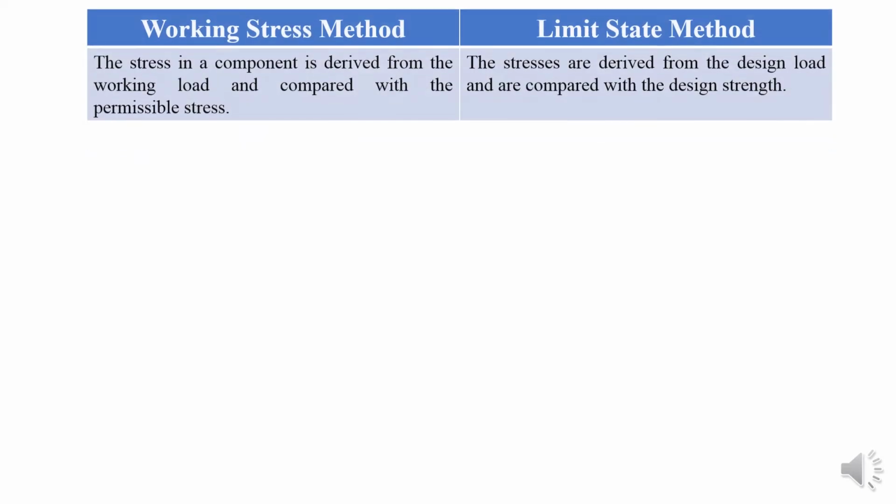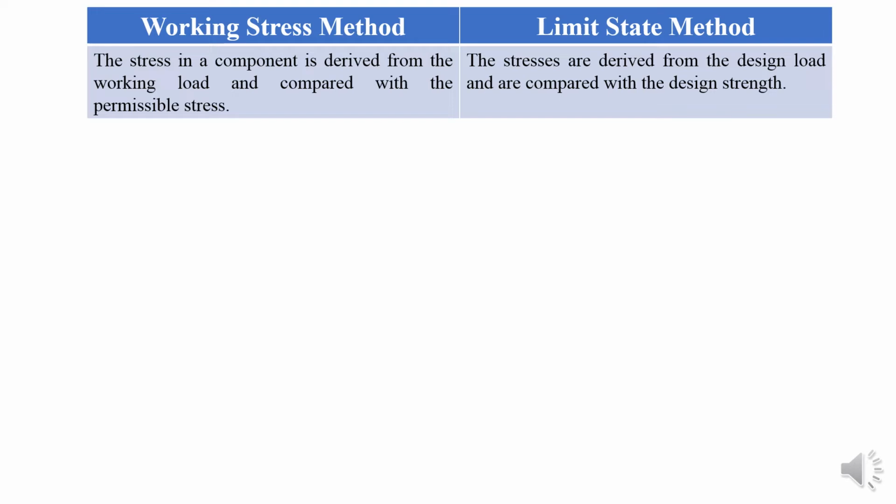We will see the difference between working stress method and limit state method. The stress in a component is derived from the working load and compared with the permissible stresses. For a limit state method, the stresses are derived from the design load and compared with the design strength.